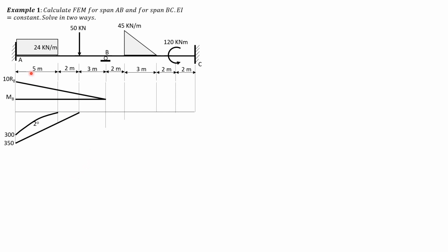So for the EI theta AB, we equate areas above to area below. By the way, for the second span, 1/2 of 3 times 45 times 1, it's 7.5 moment here. This is third degree. Now at the wall B, the moment is 1/2 of 3 times 45 times 1 plus 2, so 3 times 3, that gives us 202.5 over EI.